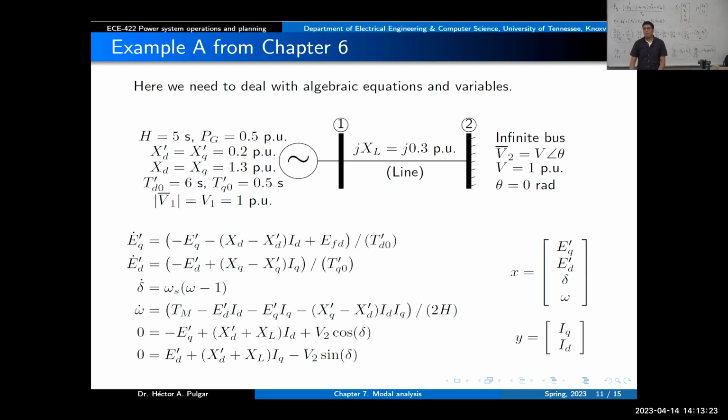The stable focus. But there is another one that is the saddle node, right? What happens when we start increasing the load? These two equilibrium points will start getting closer and closer until at one point they merge with each other and we have just one solution. Is that a critical operating point? Yeah. What happened in the system? It becomes unstable, right? So will this have an impact? Of course it will. If we start increasing the load, as David said, more power will mean that if there is a short circuit at the terminal, the machine will be accelerated even more. And that can make the machine behave in a different fashion dynamically. And the eigenvalues should change as we move forward.